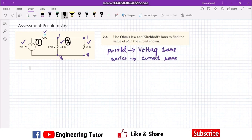So first, considering loop number 1, applying KVL here, we can see that this is minus, this is plus, this is the passive element, so here it will be positive, this will be negative, this is again positive and negative.